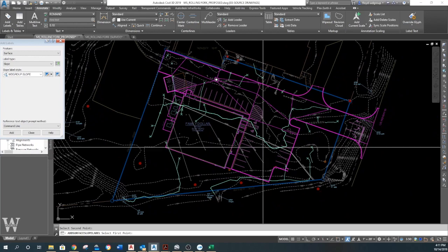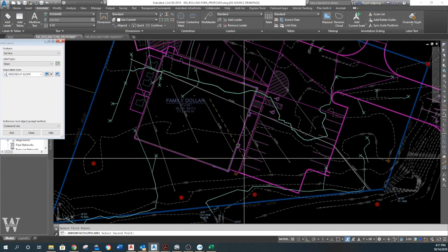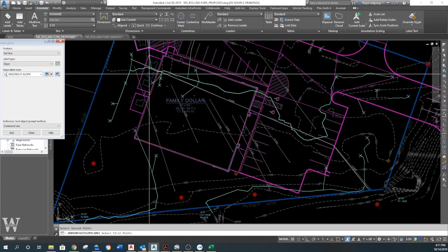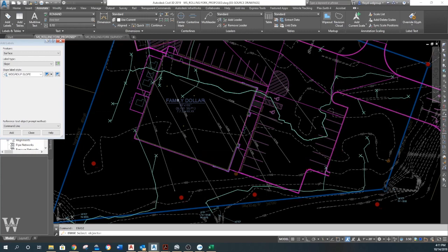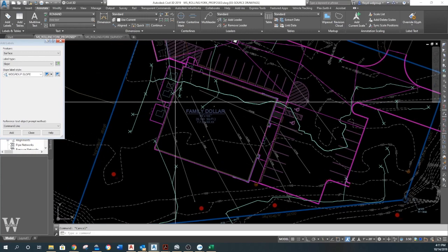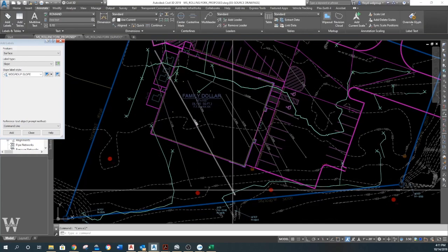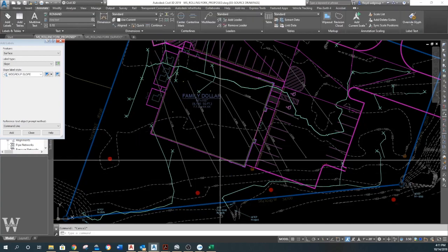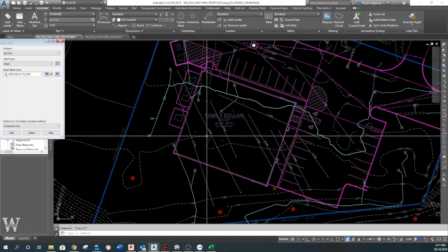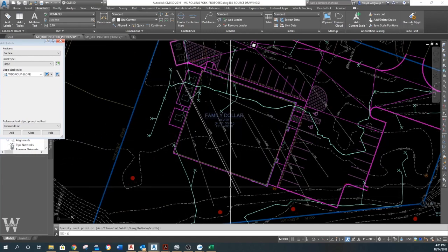You know, the flatter it is, the longer it takes for that drop to get somewhere. So we want to come off there. That water's probably going to run just like that right there. Even though that tried to go in that direction, you pretty much can say that that's going to go like that. Okay, that's probably a good number right there. I'm going to back it here so it'll be a little flatter because it gets steep here at the end. Okay, I'm going to draw me a polyline right there and get a length. So the length of that